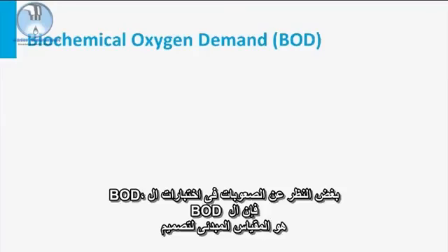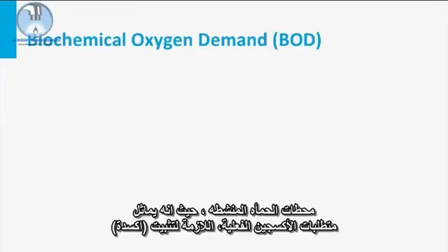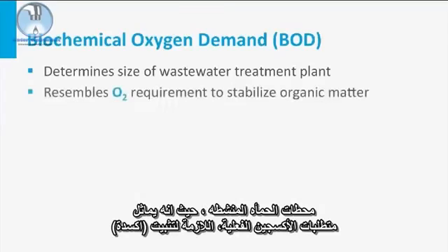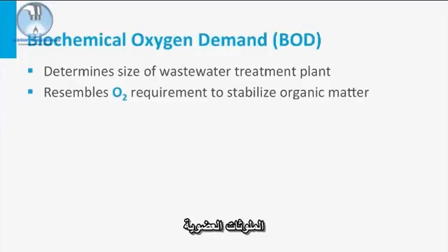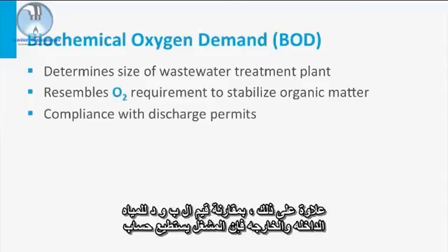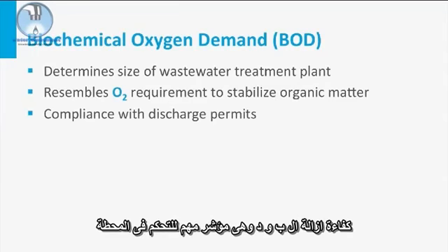Irrespective of the difficulties of the BOD test, BOD is a prime parameter for the design of activated sludge plants, since it resembles the actual oxygen requirement needed to stabilize the organic pollutants. Therefore, it is also the most important standard in the effluent of STPs. Moreover, by comparing the influent and effluent BOD value, the operator can calculate the BOD removal efficiency, an important plant control parameter.